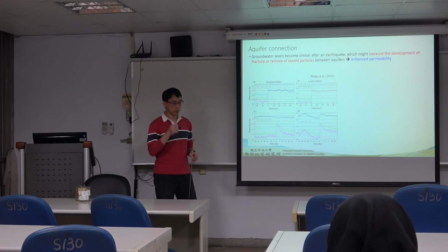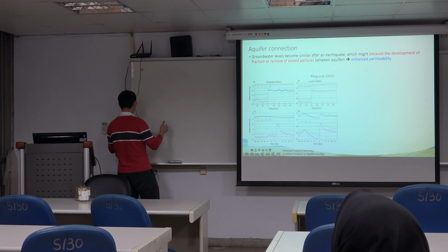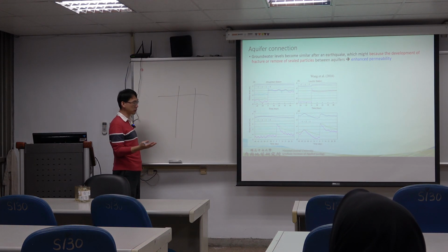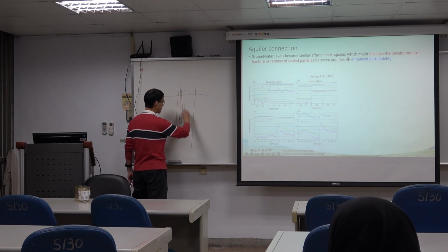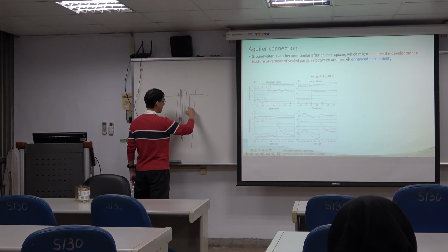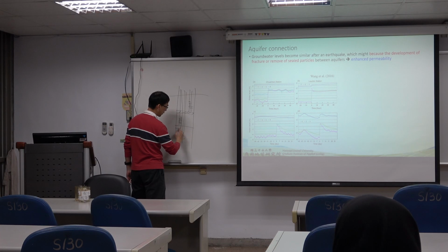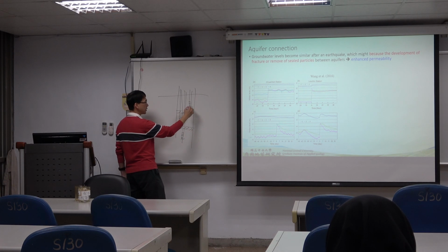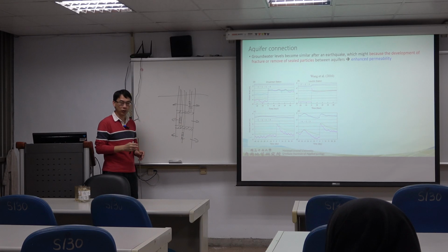Because if you know the well settings, commonly in this kind of wells, we drill a relatively big well, and we put several small wells inside, and then we seal the system. Like that. So this well's screen observes this system, and this one observes that system. So that's the original concept.